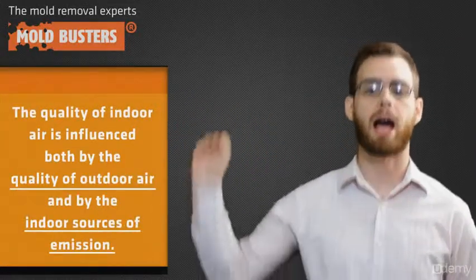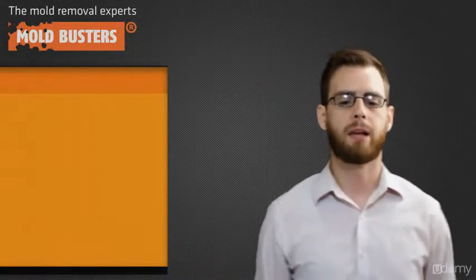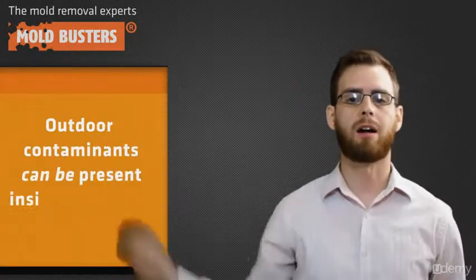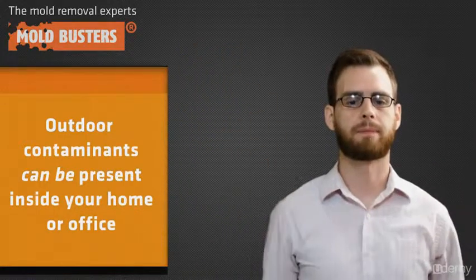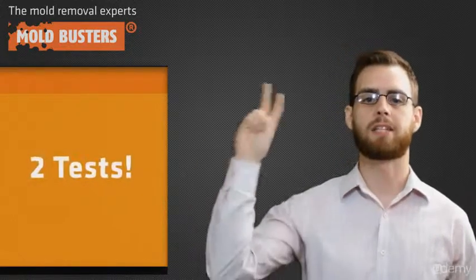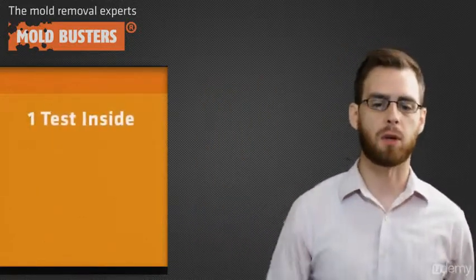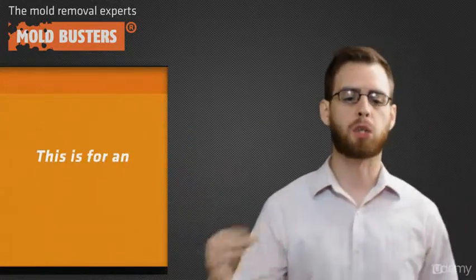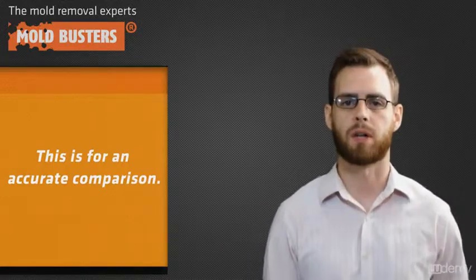The quality of indoor air is influenced both by the quality of outdoor air and by the indoor sources of emission. In almost all inhabited enclosed spaces, there is a continuous exchange of air with the outside. Therefore, all contaminants of outdoor air are likely to be present inside. This is why, when performing air quality tests, it is important to take at least 2 tests. One test indoors to test the suspected area, and one test outside. This acts as a control group against which we will compare those indoor results.